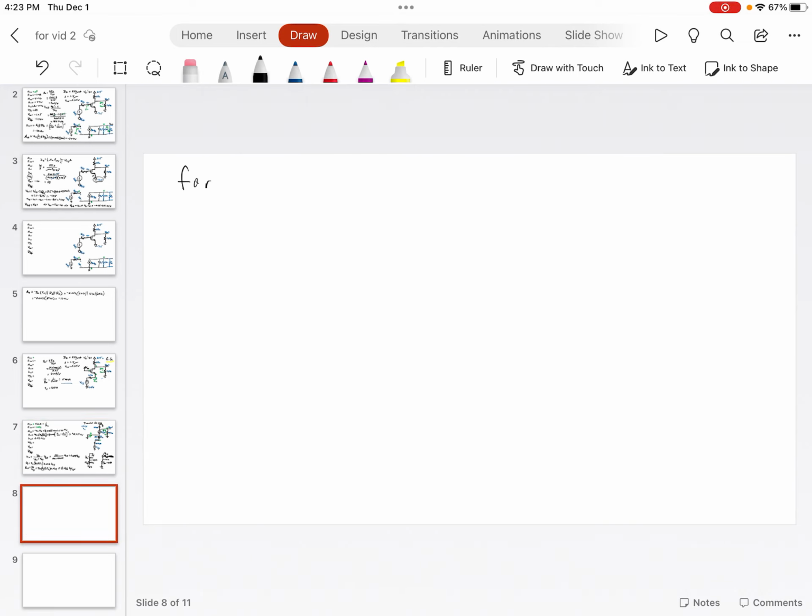So what if we had R sig equal to 100? Then we would have Vn equal to 1 over GM over 1 over GM plus R sig. If we're using the same values, then we've got 500 over 500 plus 100 times V sig, and that equals 0.833 times V sig. That's a lot better.